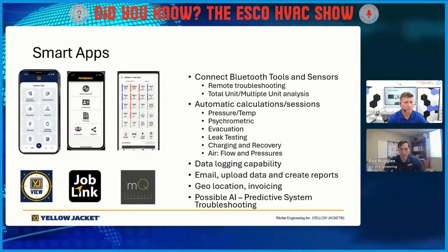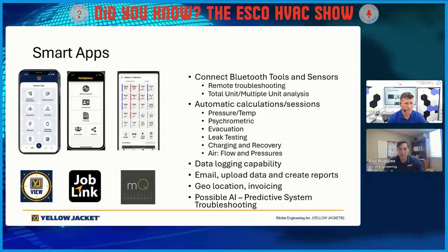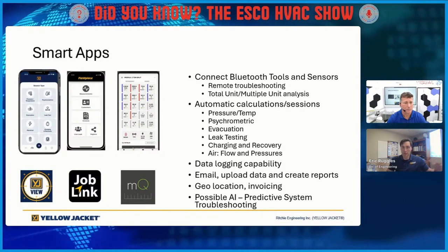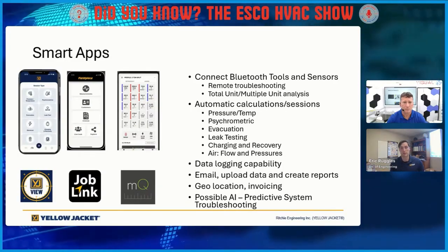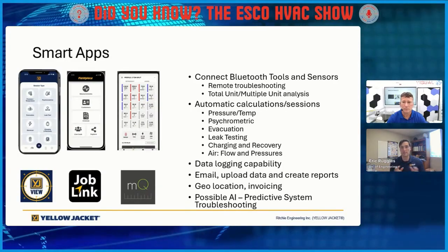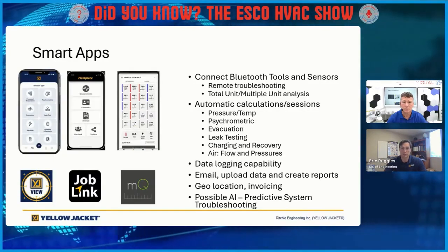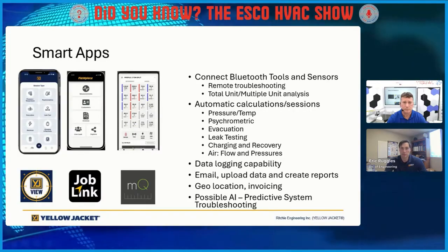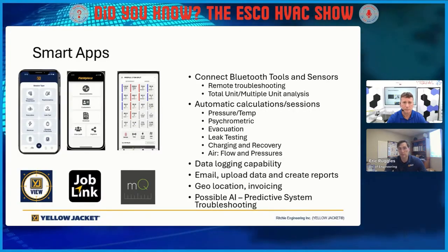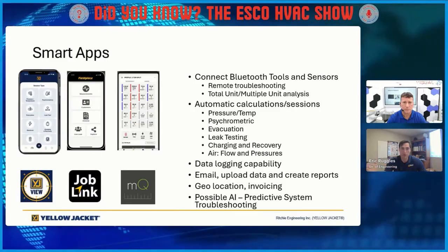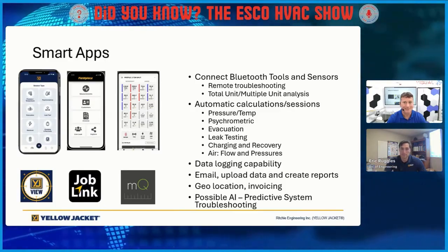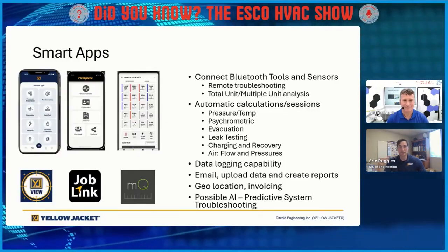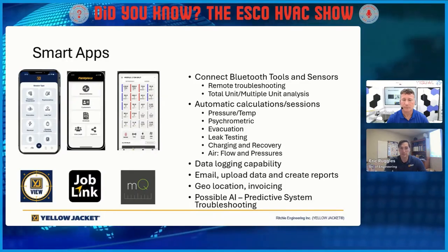Most of these come with an app or somehow linked to a Measure Quick app that can use multiple sensors, but you have remote troubleshooting capability, total unit analysis, so you can connect your refrigerant side and your air side sensors all at the same time, and then kind of review the whole system within just a few clicks on your screen. We have multiple sessions, whether you're doing pressure and temperature, the refrigeration, psychrometrics of the air, evacuation, leak testing, kind of all automated within the app. We can walk through that a little bit later. Yeah, definitely. Data logging capability, emailing, uploading, creating reports that you can send to either your supervisor or send to the customer themselves, et cetera.